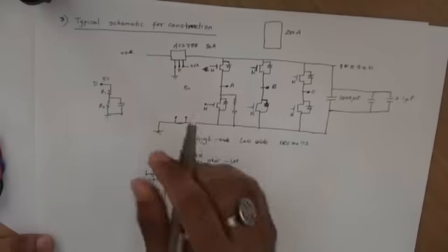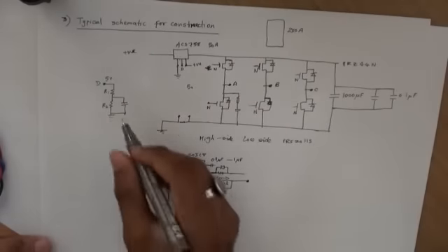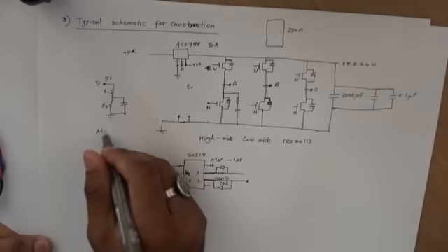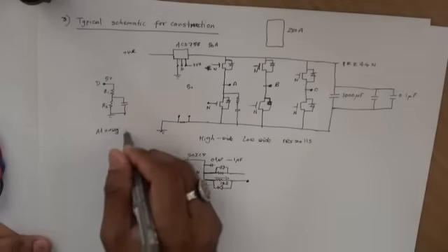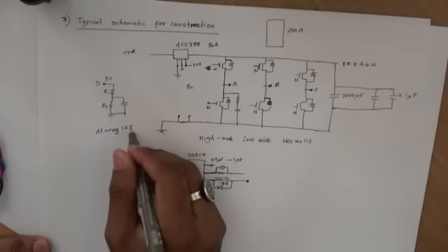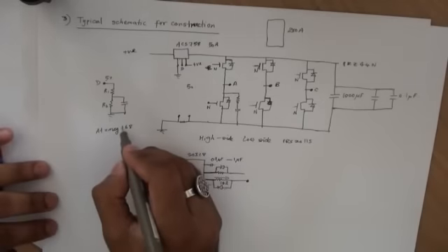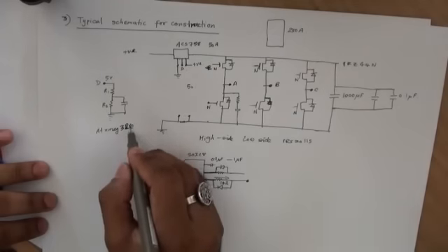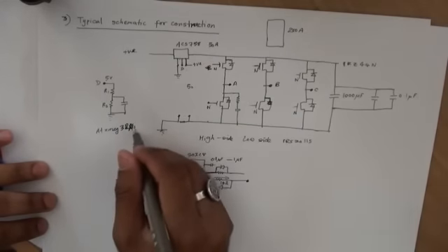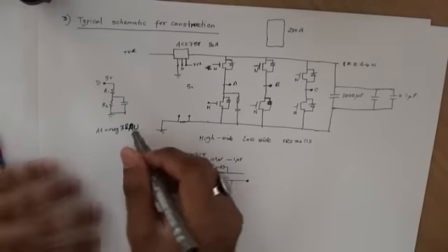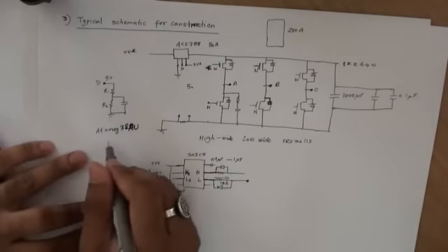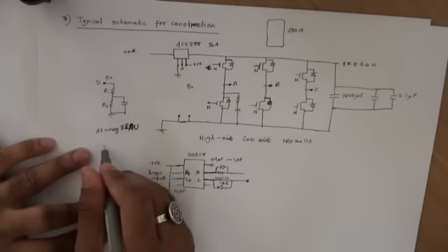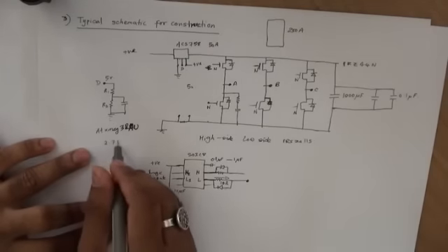So in my case, in my later design, I have used the Xmega 32AU. And these tend to have a maximum ADC level tolerance of 2.7 volt.